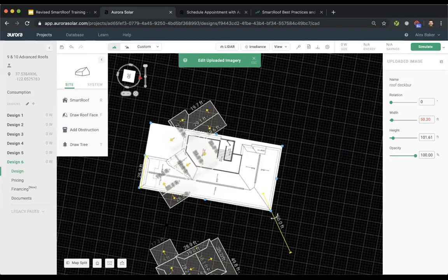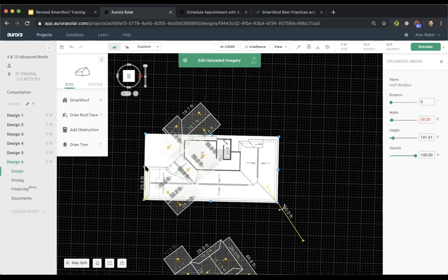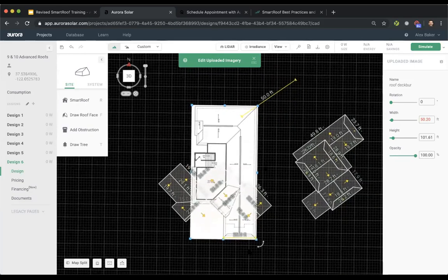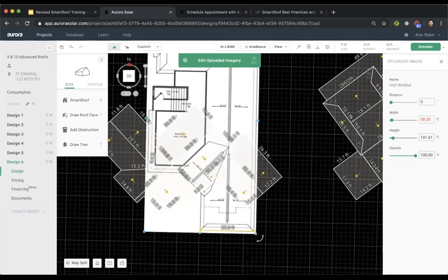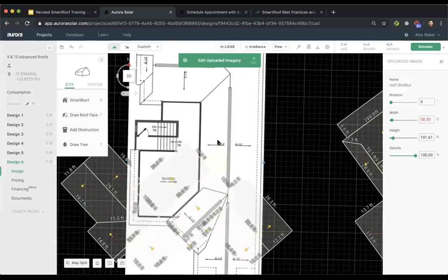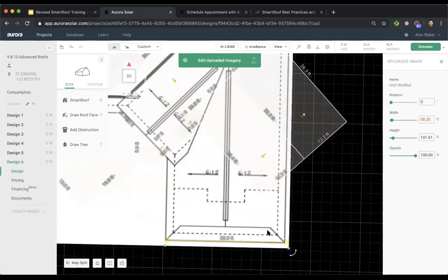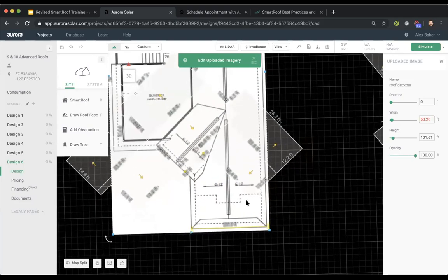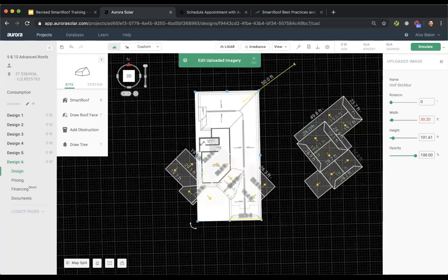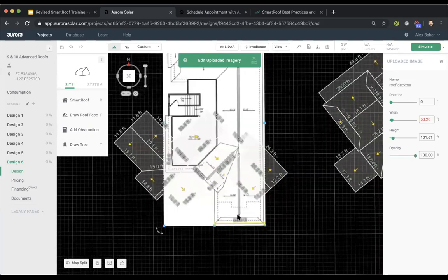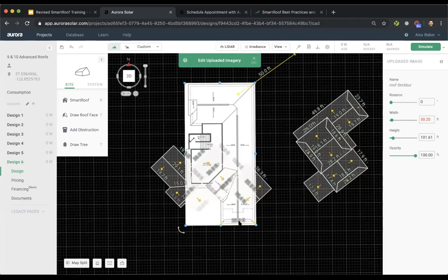And then at that point, you would just use our SmartRoof tool to trace out the perimeter. And of course, you want to make sure you get all the corners. Hopefully with your plan set, you have some images of street view or the front view of the house to get a better understanding. But this one actually has the slope measurements in there, so that would be helpful. Looks like perhaps there's a vertical fold here. A little bit hard to tell, so obviously you can't completely draw it just from a top-down roof outline, but if you do have additional imagery, once you scale this, I utilize that to make sure I have an accurate model to represent the design plans.